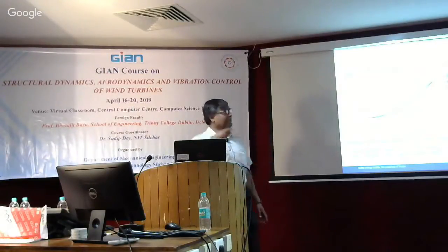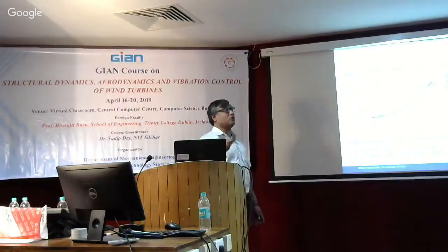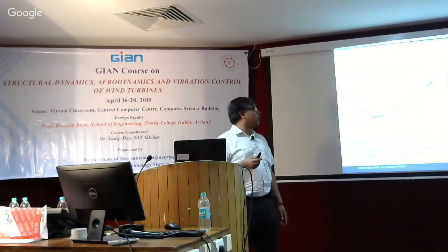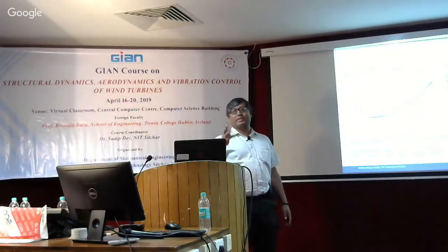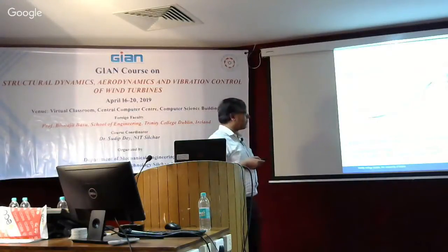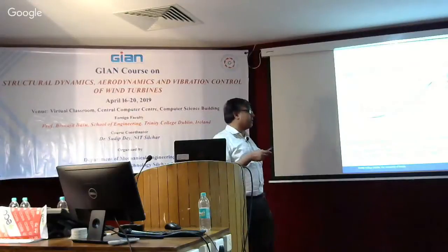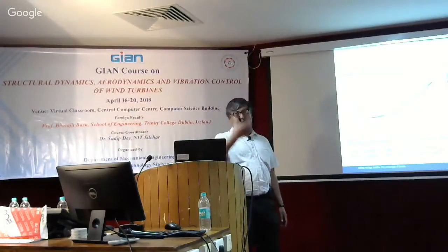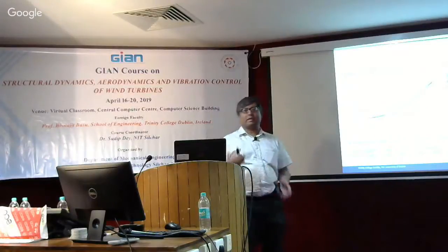And we have actually, not in this one, but another paper in Royal Society we published. I'll give you a list of a few key papers we will follow, where we did look at this coupling of the modes and the twist. Because if you have this, then there will also be torsional modes coming. But if you want to get that, then you cannot use the Bernoulli-Euler beam equation. You have to use shell to model the plates as well.